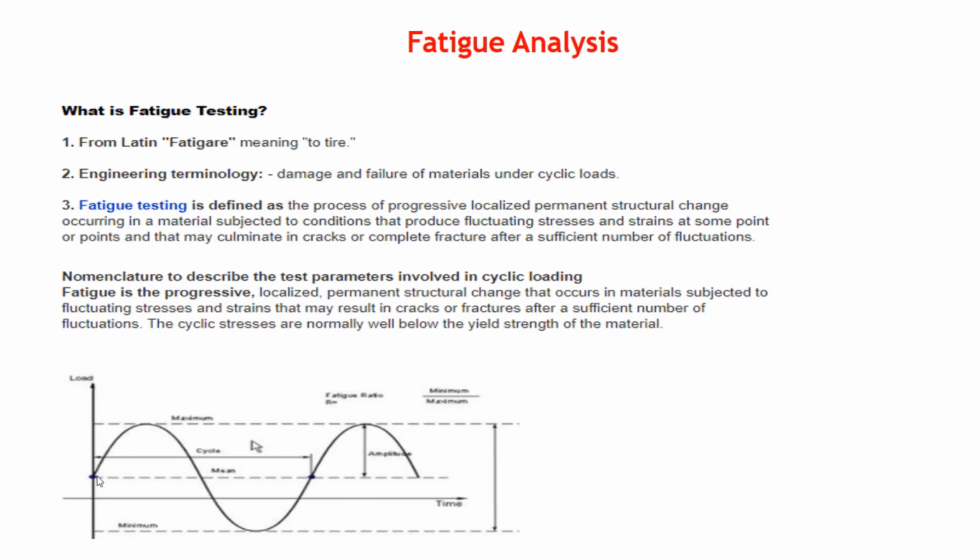Initially it will load up to a certain loading condition, let's say from 0 to 1. Let's say I'm applying 500 Newton, 0 to 500 Newton, and again it will come to rest. In the sense, the loading will be removed. It will not go to minus 500 Newton downwards, as you can see in the curve. That is 0 to here, like this. So that is known as zero based.